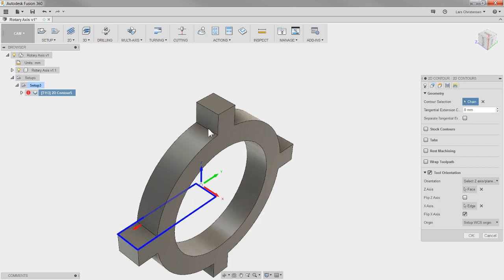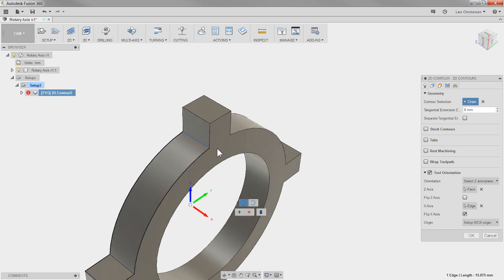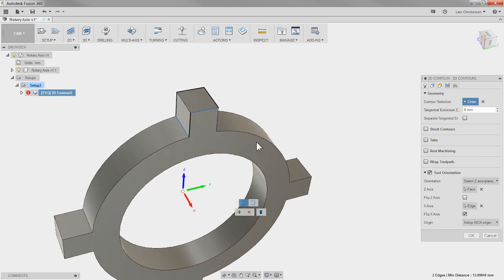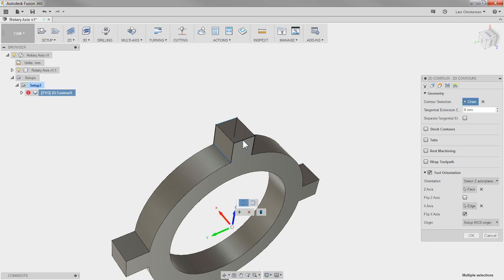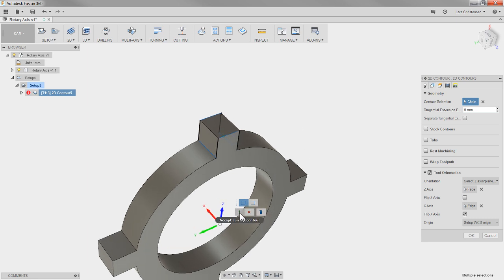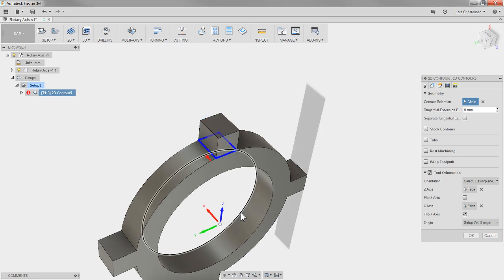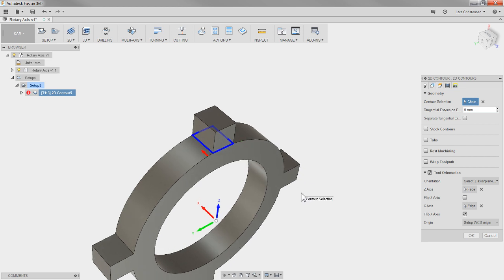I actually can't select it up here. I have to select that edge again, and then this light blue ends up, and now I can go around. I can select this one because that's the edge that I would like to get projected down here, and I'm going to machine or click around here and up here, and then when I remember to hit the plus sign, it will project it down.